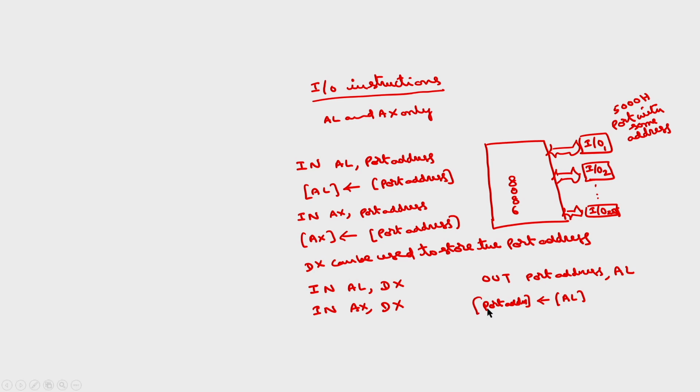If the port is an 8-bit port, then AL contents will be transferred. If the output is a 16-bit port, we have AX.